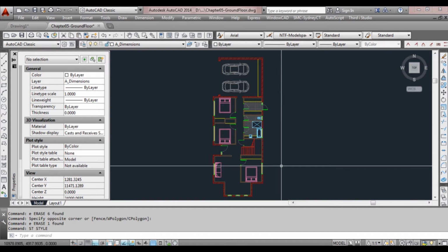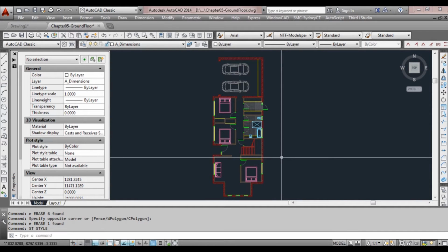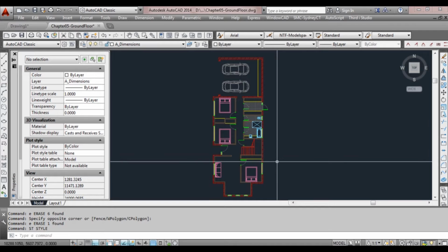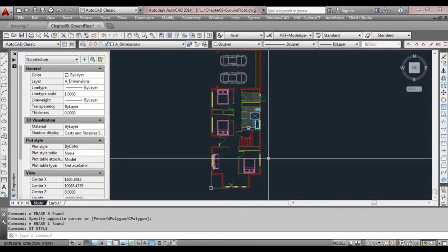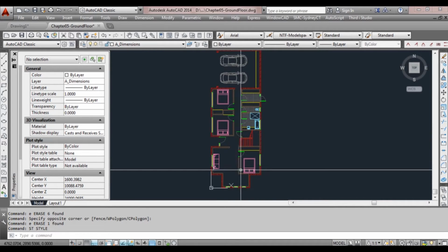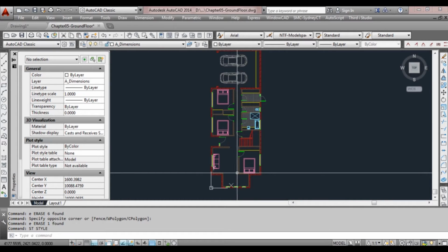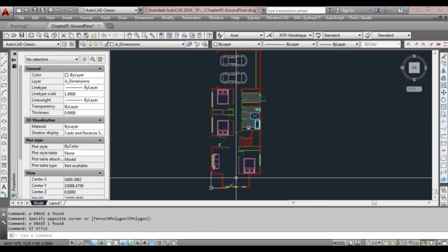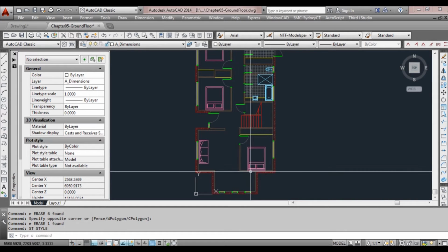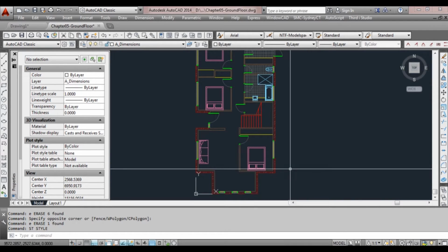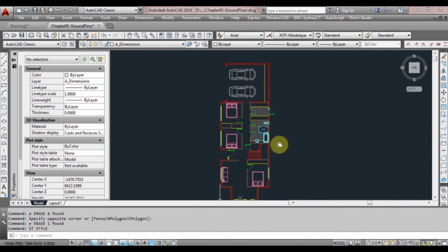In this exercise, we're going to apply some room names using text, and we will do some dimensioning as well. At the moment, we're going to put the text and dimensioning inside of model space. You can actually put it in paper space too, which we haven't talked about yet in the course. There's advantages and disadvantages to both ways, but for now, just for clarity, rather than getting too deep into paper space right now, we're just going to do the text and dimensions in our model space. So here I have our ground floor plan.